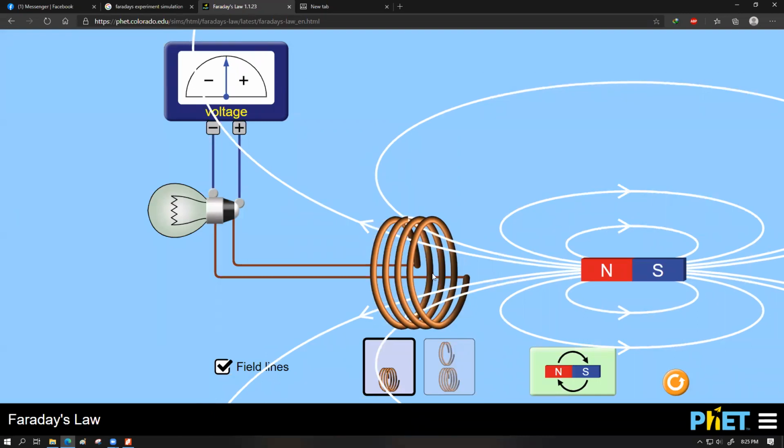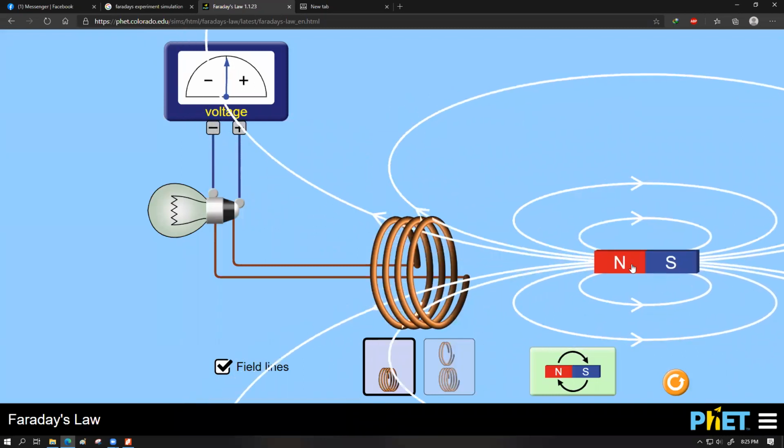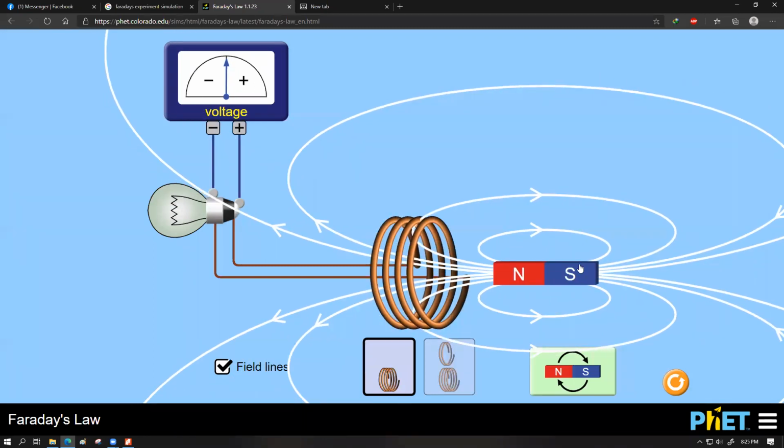And then Lenz actually gave us a solution. He said that no, energy is not being created. It is the kinetic energy of the magnet, in this case for this animation, or we could alternately keep the magnet stationary, and if there is a way we could move the coil around, that would also be possible, which is also a design aspect for many of the AC generators that we have. There has to be some sort of relative motion between the magnetic field and the coil. That's all that matters. You could move the magnet, you could move the coil, or you could move both of them in opposite directions simultaneously. That also depends on how you want to design this field.